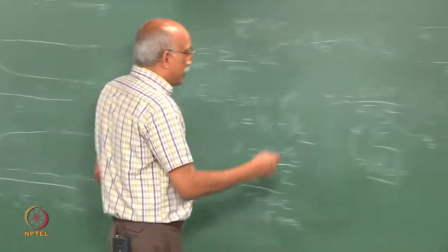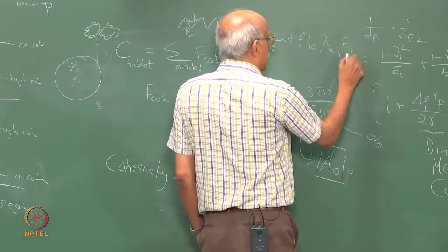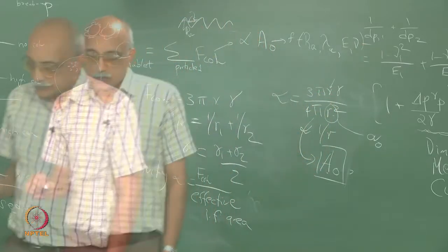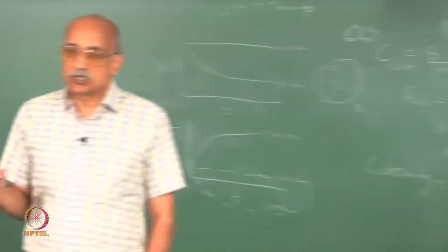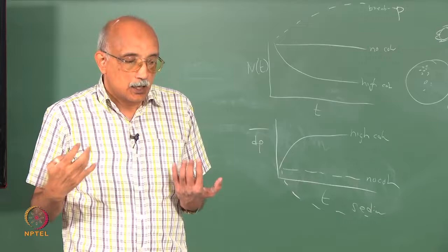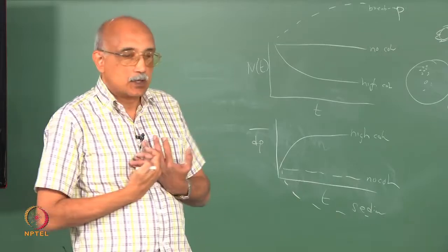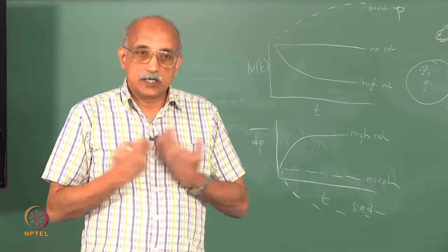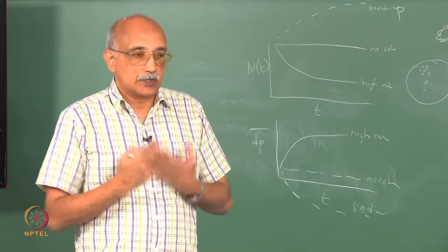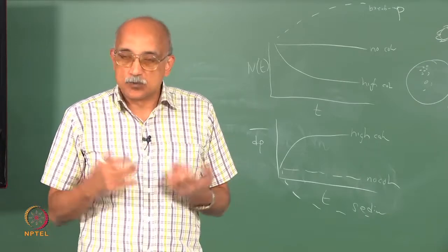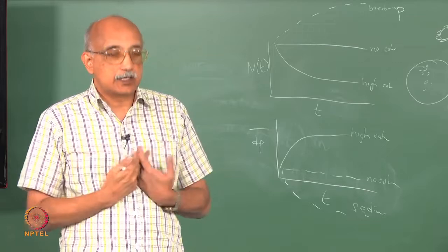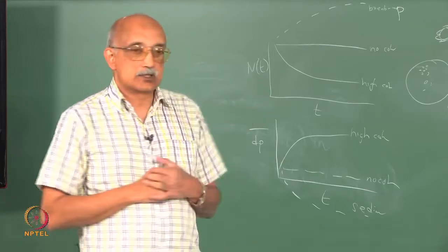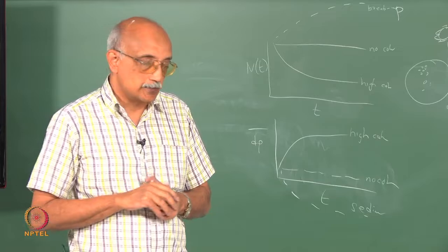And of course, other parameters like elasticity and Poisson's ratio are also important, because just like adhesion, cohesion also depends upon how the two particles react. Is there any give as two particles approach each other? Are they going to present very hard surfaces to each other, or are they going to try and accommodate each other? The more accommodating the particles are, the greater will be the cohesive force that develops. So, clearly those parameters are also involved in this expression.